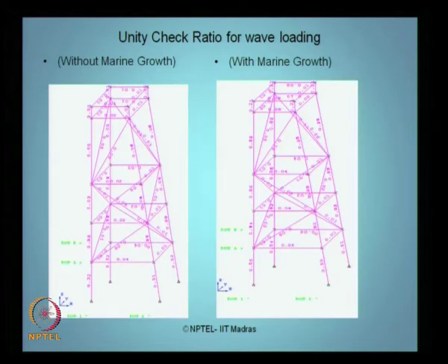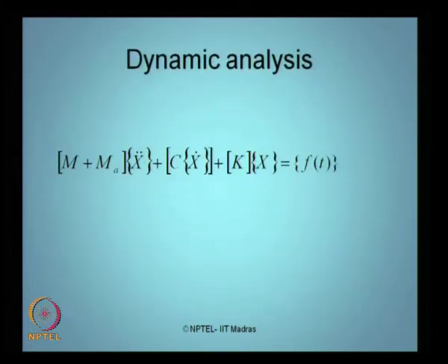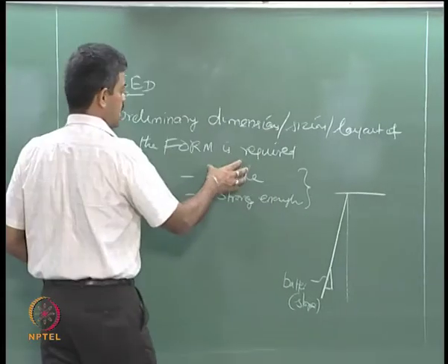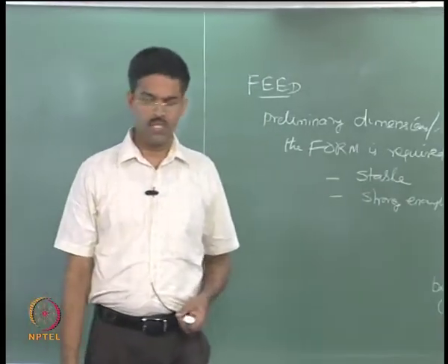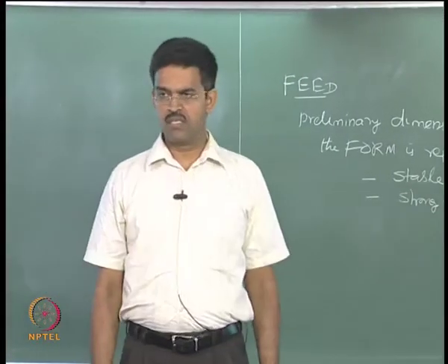If it fails, you have got to change the section group or the dimensions or the characteristics of the member or the entire group, once again redo the analysis, run the analysis once again and see whether unit check has been approved. So, unit check is where we are saying that the structure has become stable to understand the configuration and the members are strong enough to withstand the bending or axial stresses applied on the member.